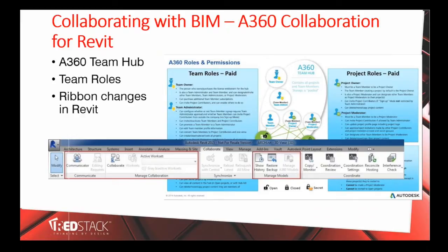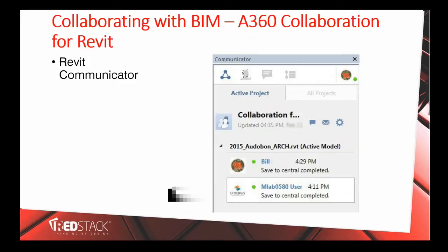Once you enter an A360 Revit project, a new communicator panel becomes active, which enables a live chat feed to all members that can share communications in real time. So depending on the model activities, these can be managed typically by the Manage A360 Models button on the Manage Models panel. You can view version lists of all versions of the model, and each sync creates a new version. The version will capture the date, time, and member's name as appropriate.